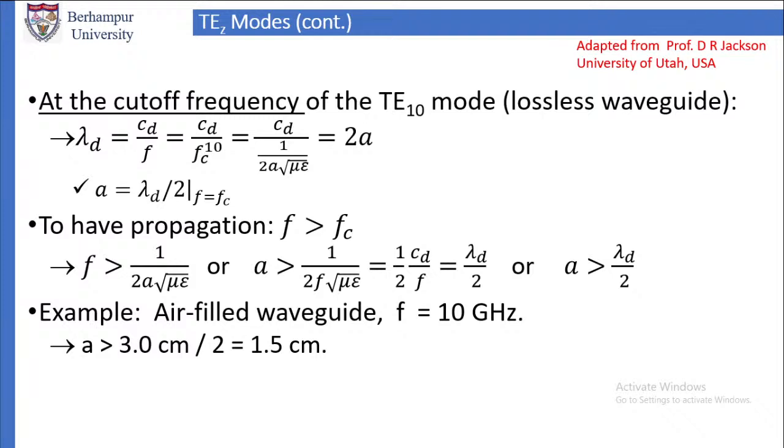Now, at cutoff frequency, what happens? The mode is TE10 mode. This is the dominant mode, the lowest cutoff frequency, and we are considering a lossless waveguide.